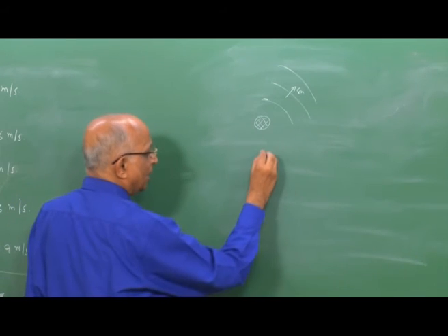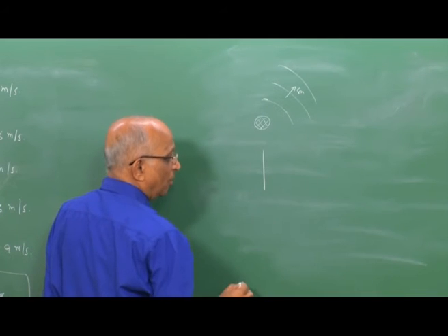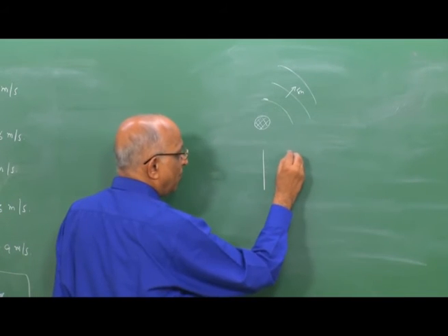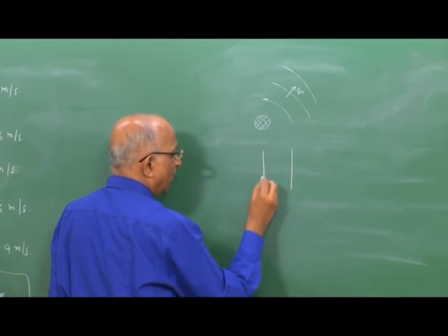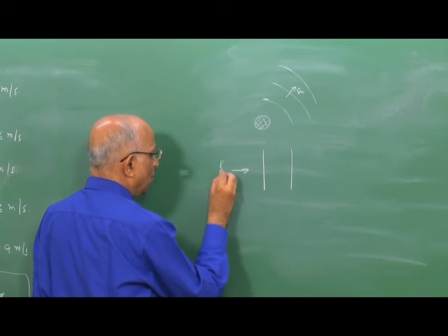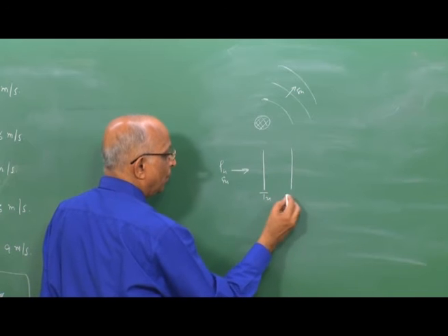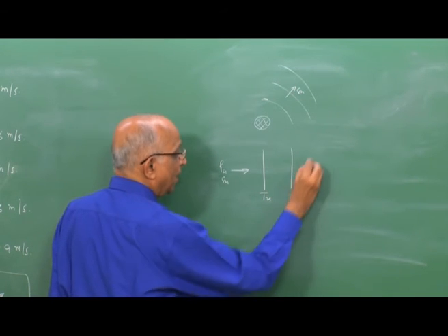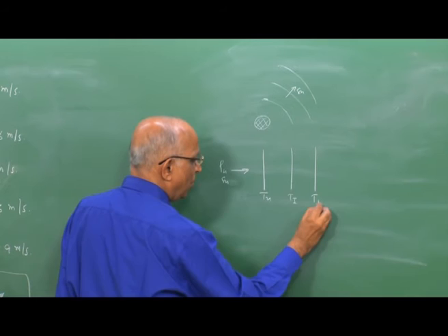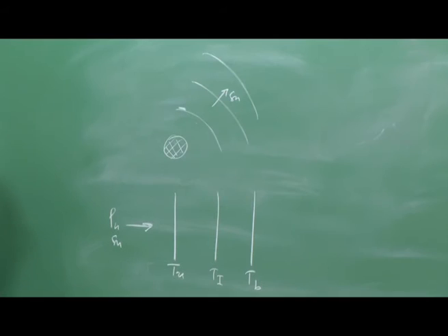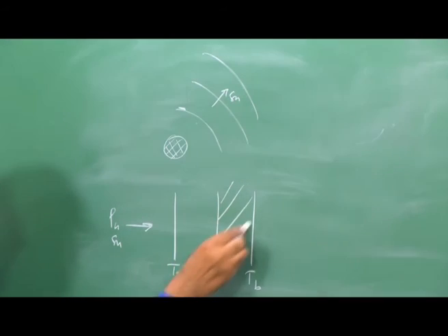Therefore, I am interested in the thickness of the flame. Let us again put the diagram of the flame as we looked at it earlier. Well, I say rho u into SU comes here, it increases in temperature from Tu to an initial value Ti to the burned gas value Tb over here. Therefore, what is happening? This is the zone of length L in which chemical reactions are occurring.